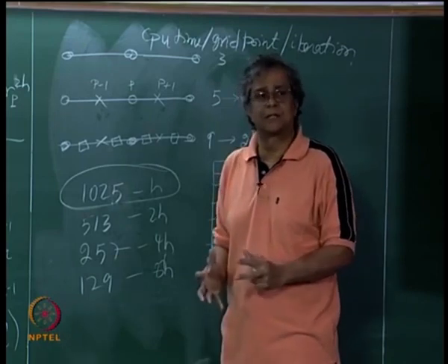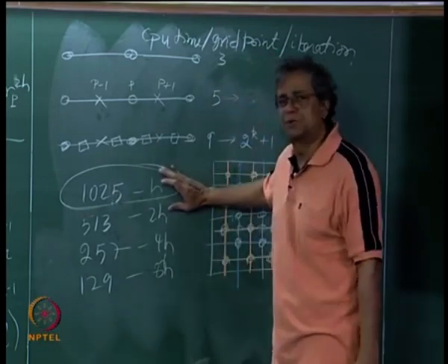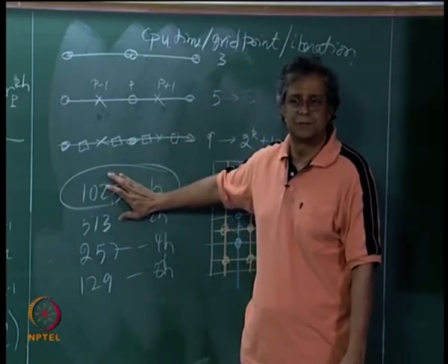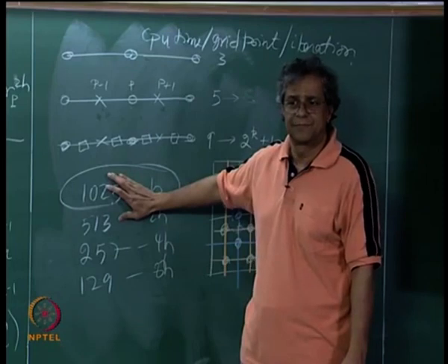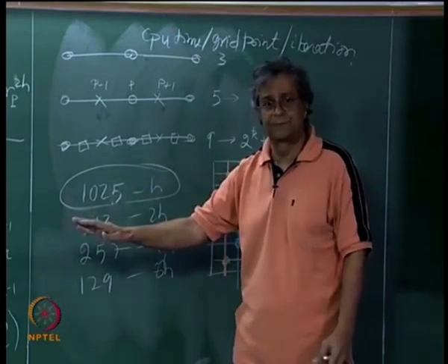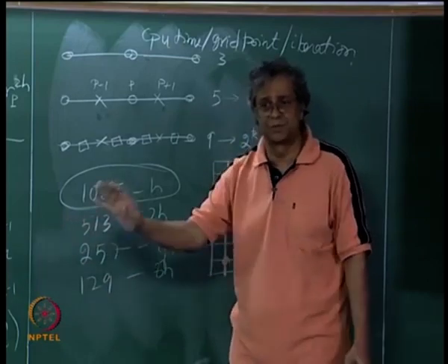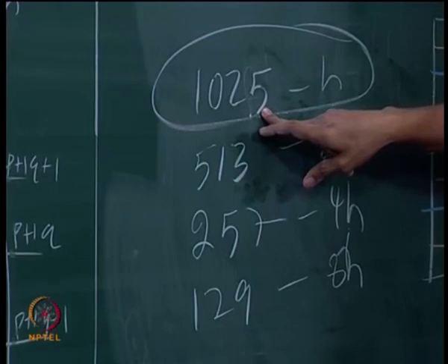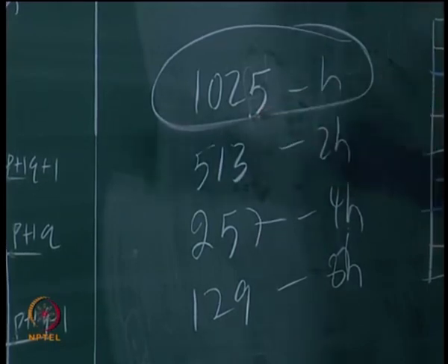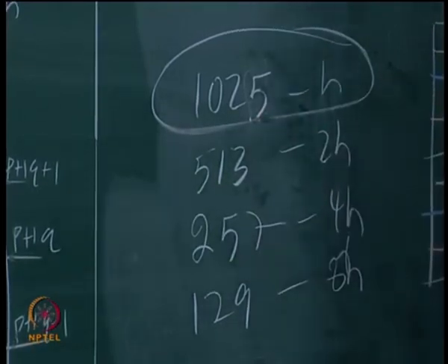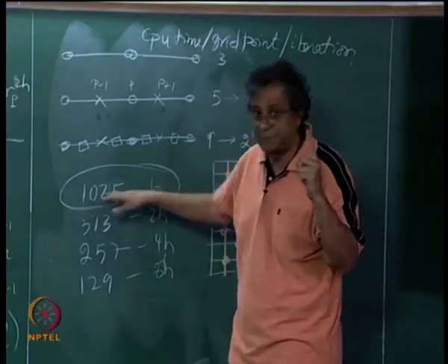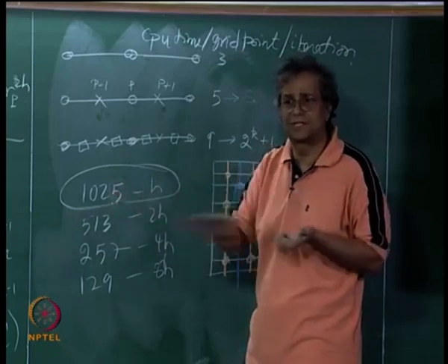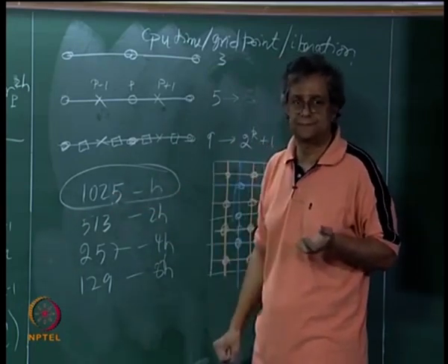So now I want to get a measure, right? So I will say, wait a minute, if you didn't do multi-grid, you would be doing so much work on 1025 grids. So I will call one sweep or one time step or whatever scheme that you are using through this 1025, your finest grid, I will call that one work unit, right. We will start off by defining what do I mean by this work. So we will call that one work unit. Am I making sense? Sweeping through your finest grid, making one iteration or one time step, I will call that one work unit.